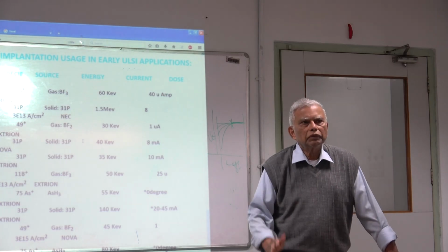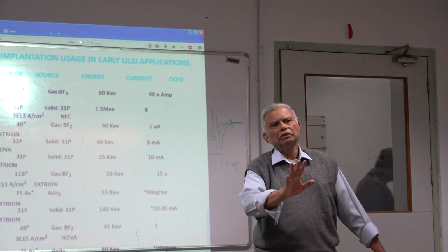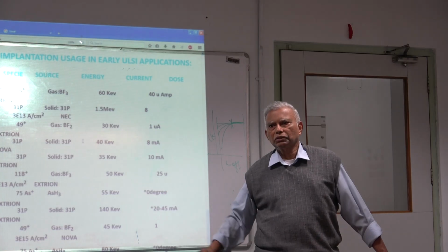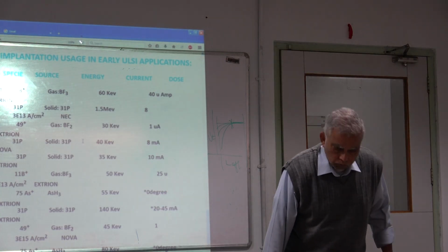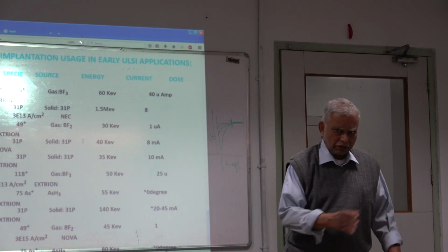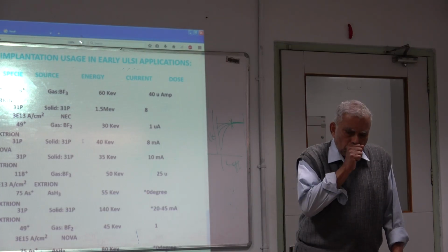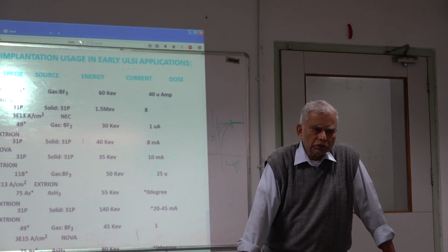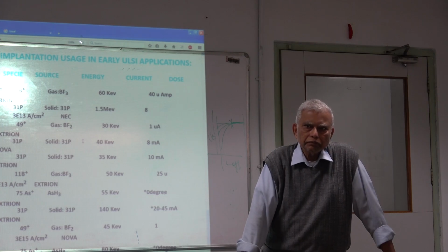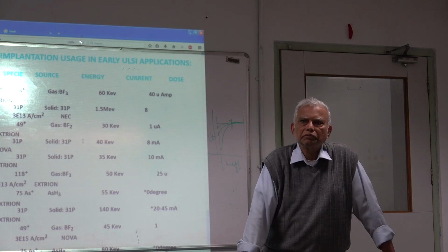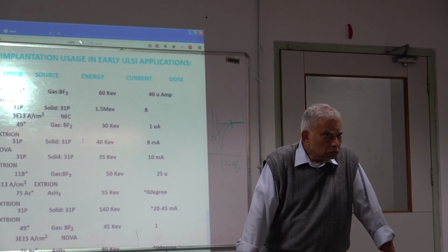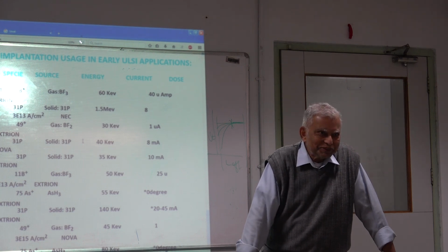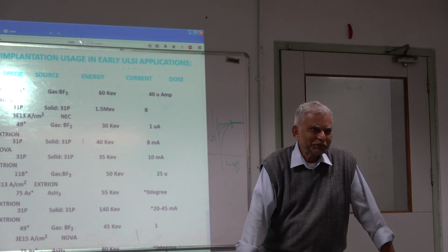So what we used to do at every step on the way, we'll take some wafers, push them through the entire thermal budget, and then make all the measurements at the end. These are ways of evaluating whether we're on the right track or not. It's very cumbersome, there's no better way. Because we wanted to reduce the thermal budget as much as we can until we attain our goal. Because if you don't, we run into more fundamental problems, right? For channel effects.